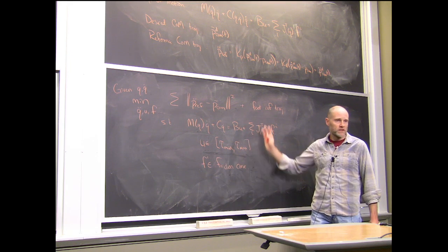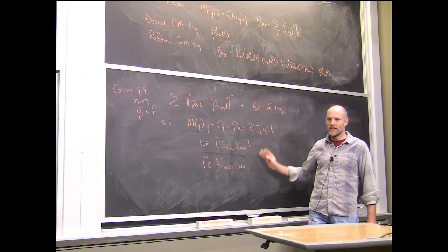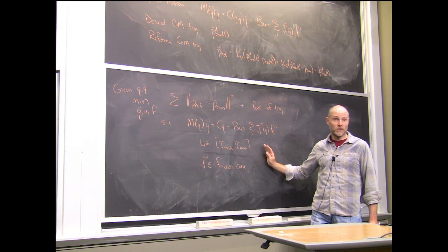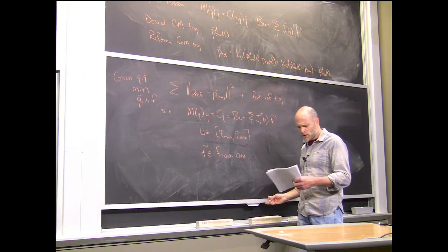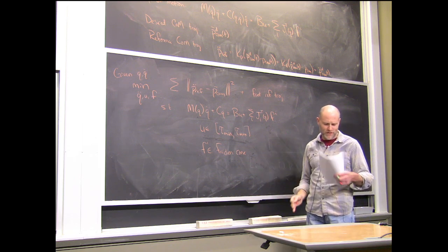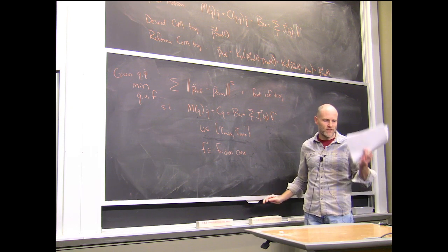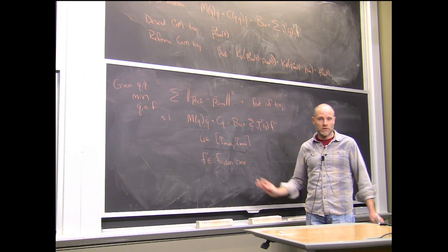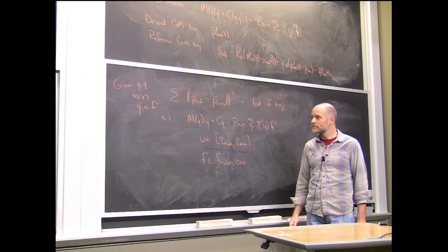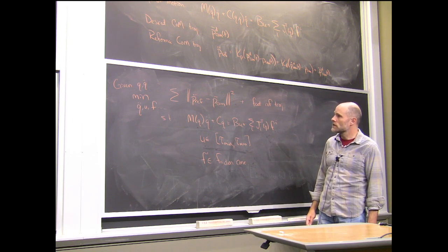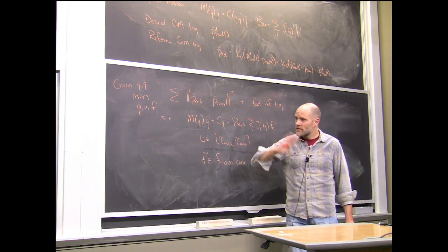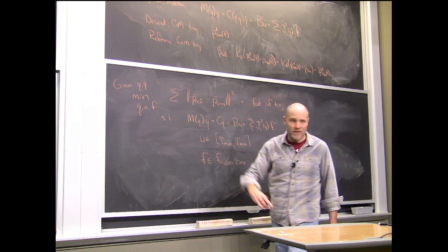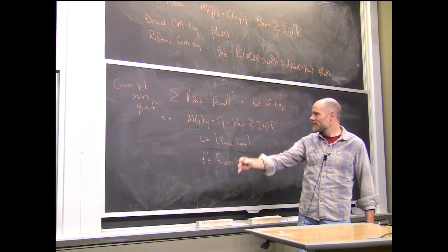And all the groups that were working on Atlas at the time sort of started converging to these kinds of controllers. These worked. This was definitely one of the lessons of the DARPA challenge, that these controllers work extremely well. Our QP had like 90 decision variables and 30 equality constraints and 112 inequality constraints. I looked it back up and wrote it down, and that was completely compatible with online computation. So it's amazing that it took this hard, nonlinear, long-term optimization, and by breaking it up into those pieces, we got to something that we could just plan on the fly and stabilize pretty well.